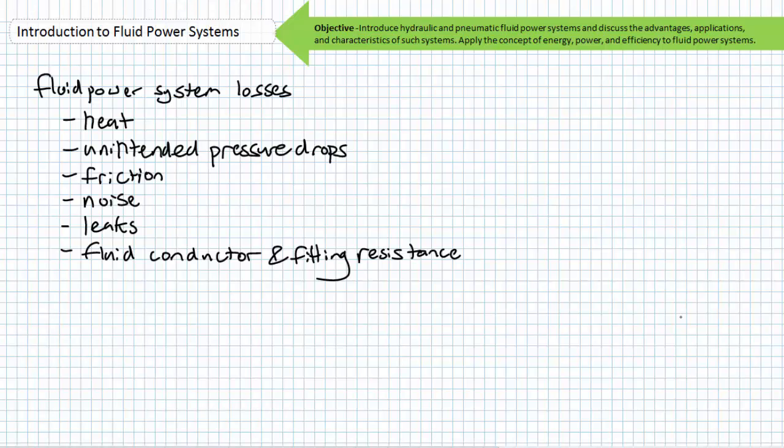However, complexity and accounting for inefficiencies can be an acceptable trade-off if one form of power transmission presents notable advantages over others. When it comes to rotational actuators, the electric motor is my weapon of choice. I am not going to build a high-range electric car driven by a hydraulic motor. This being said, an excavator with a fluid power system driven by an internal combustion engine can power rotational actuators and a harvester attachment to cut, limb, and manipulate a huge tree without the necessity of powering an electric motor.